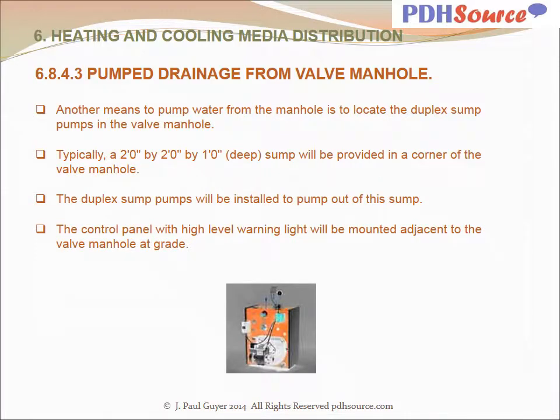Another means to pump water from the manhole is to locate duplex sump pumps in the valve manhole. Typically, a 2x2 by 1 foot deep sump will be provided in a corner of the valve manhole. The duplex sump pumps will be installed to pump out of this sump. The control panel with high-level warning light will be mounted adjacent to the valve manhole at grade.